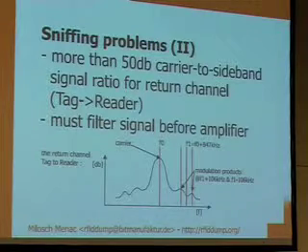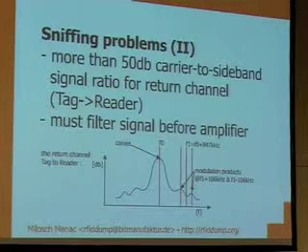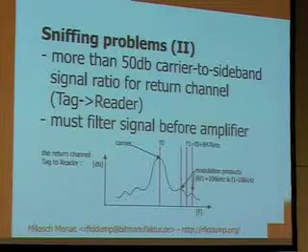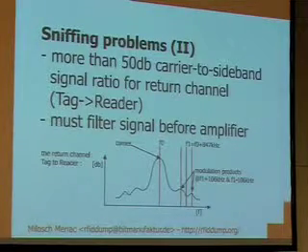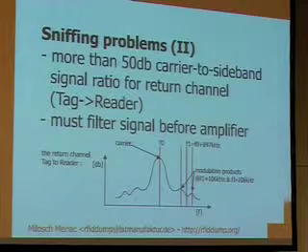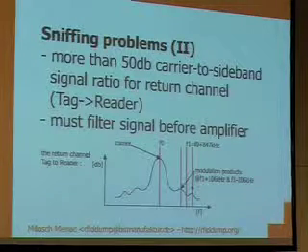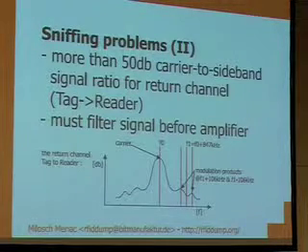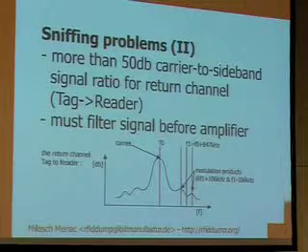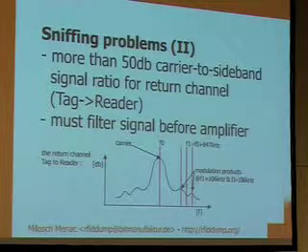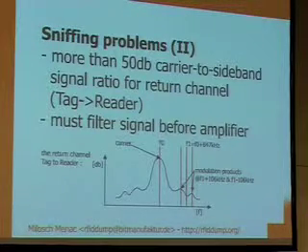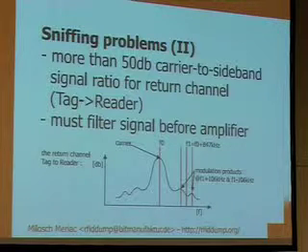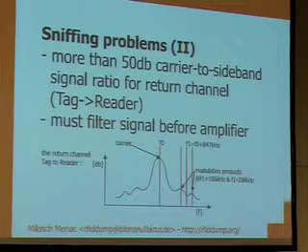The reader, and this 800 kilohertz frequency on the tag side, is turned on and turned off by the given baud rate. There are several baud rates. One common is 106 kilohertz. So this 847 kilohertz shifts around this F0 plus 847 kilohertz, plus minus 106 kilohertz. So in fact, you see this diagram, and if you want to see the data transmission coming from the tag to the reader, you actually have to look at the sidebands.